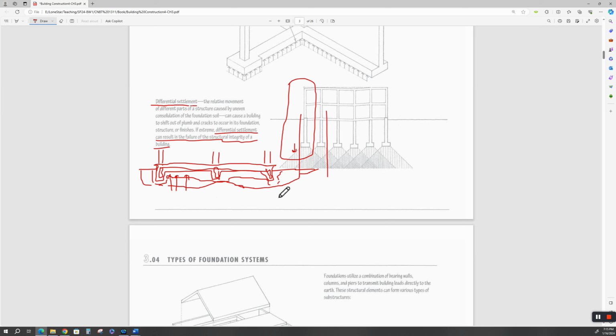Unless, of course, you've got a giant oak tree out here that you just had to save because your wife likes the oak tree, and these giant roots continue to grow under your slab and eventually start putting differential pressure on your slab, and you have upward movement on your slab, which is the same as settlement, except it's going in the opposite direction. Because here's a tree, okay? So the roots will push up on the slab, which is the same as settlement, it's just going upward instead of down. It's just as bad.